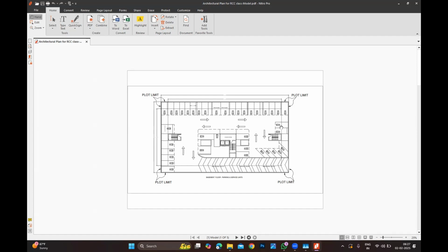Don't ever start your column from the basement, because placing the column in a basement is a matter of seconds. It is very easy, because every 3 parkings or every 2 parkings you will have an island, meaning there is a separation, a small interlock. Placing the column in the interlock is very easy; anybody can do it. The challenge is where you place the column in the upper floors, whichever has the majority. So let's say the 8th floor is typical, we will start the column from the 8 floors. This is the first point.